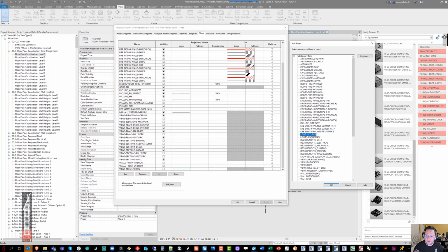There are two filters for light fixtures, and their purposes are in the reflected ceiling plan to add poche to the light fixtures to make the RCPs pop graphically a little more. This is better than using a symbol or a diagonal line across the light fixture, since that depends on the content being built a certain way, and using a VG filter over the top of the light fixture simply requires that it be a light fixture.